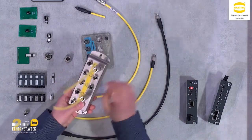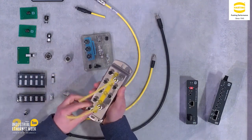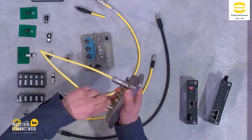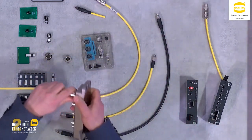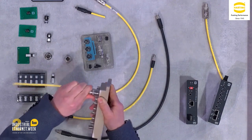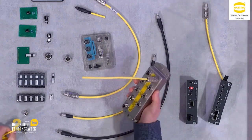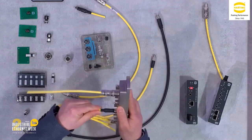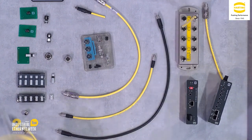So also here you see we have 7 ports for SPE. This can be used for 100 megabit and gigabit. And what you see here also is the M12 connection with the screw locking. And we also have a push-pull locking, which is much easier to connect in the field. But also interesting to know, if you want to test or set up your devices, you can still connect the IP20 interfaces here. It's also locked. This is a very nice feature for setup and to test some applications.